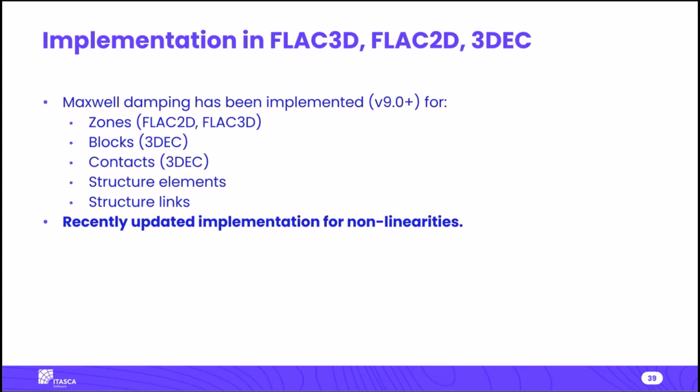Maxwell damping has been implemented in many elements, for example FLAC 2D and 3D. It has been implemented for solid zones in FLAC 3D, blocks and contacts in 3DEC, and also for structural elements, as well as structural deformable links. Very recently, we updated the implementation for non-linear behavior, as Ethan already presented.